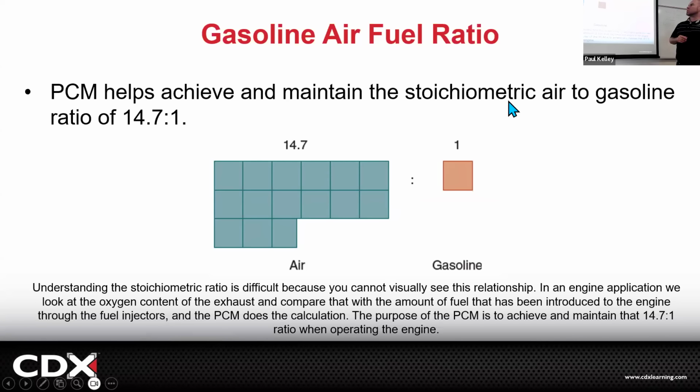Stoichiometric, or stoichiometric, you can pronounce it several different ways. Okay, so that's our ideal, and it's a little different, by the way, for ethanol, and it's different if we have different variations. It's the same for 91 and 87, but if you have like E85 or E10 or E50-50, it changes if it's a different ratio of gasoline to ethanol. But if it's gasoline, it's 14.7 to 1. Okay, so we're going to be chasing that one.